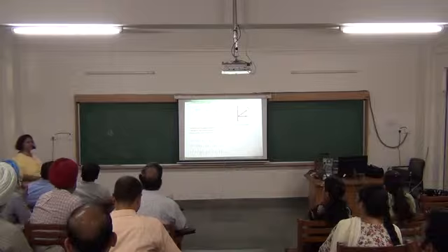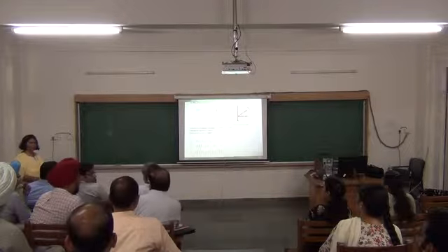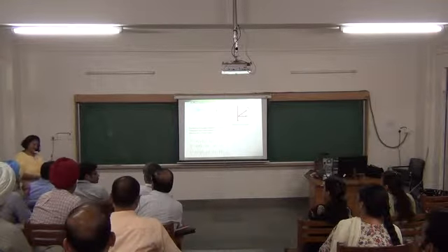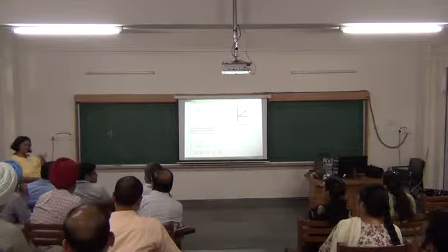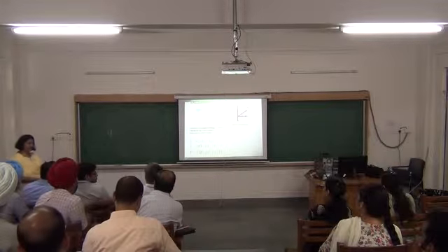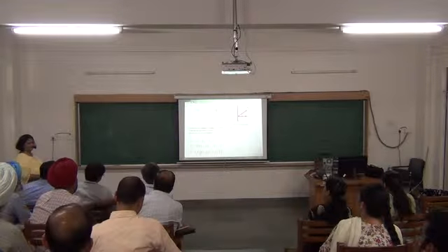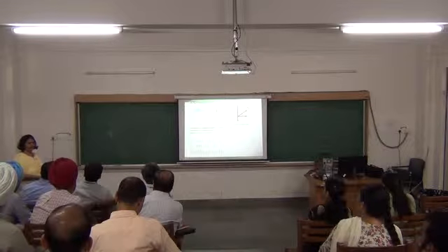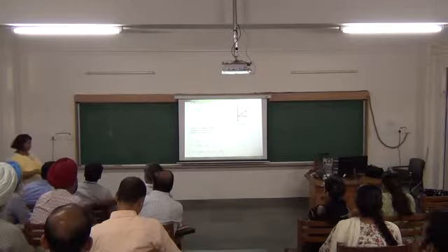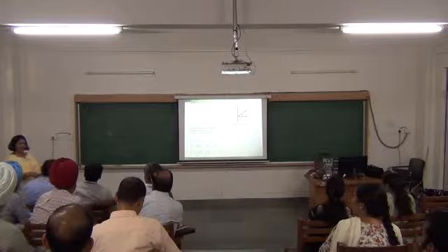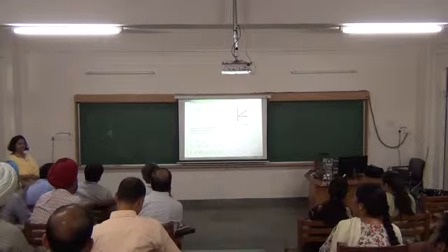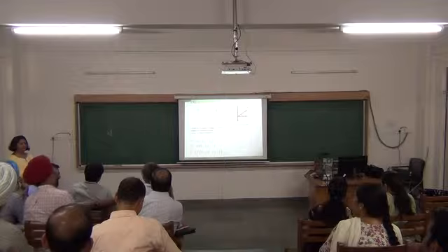Then you take the negative. Most of them will show V_L minus V_C. That is the reason, because X_C is negative, it is showing my negative phase. So the negative sign shows that it is lagging and this positive is leading. Mathematically it doesn't matter, but physically it means that X_C is lagging and X_L is leading. That is the mathematical part here.